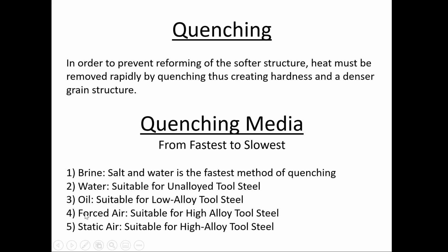And now when we get into the high alloy stuff, we've got to be careful dropping anything in any form of liquid. It'll shatter. I've seen them jump right out of a quenching pot just because somebody took a piece of D2 and had it up hot enough, and it actually shattered inside the liquid and put the liquid all over everybody. And it was oil. There were about 4 people in the area, and everybody had oil on them from this thing.